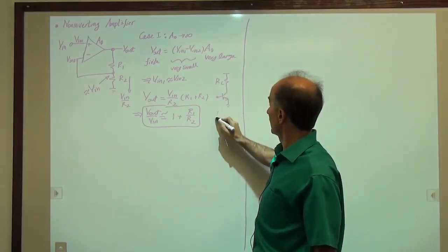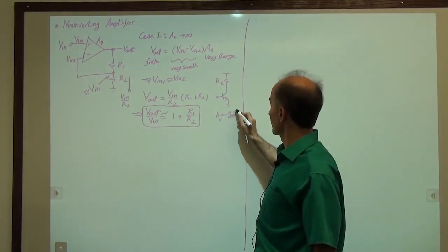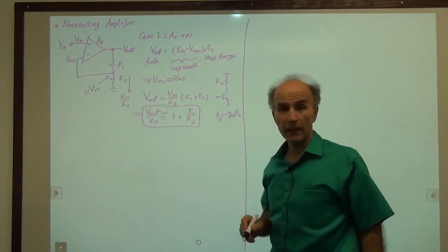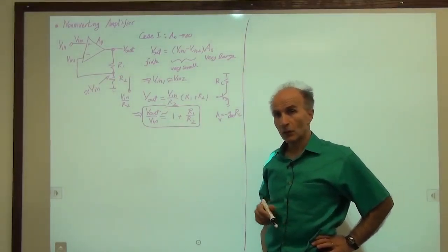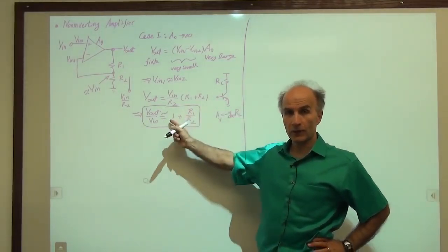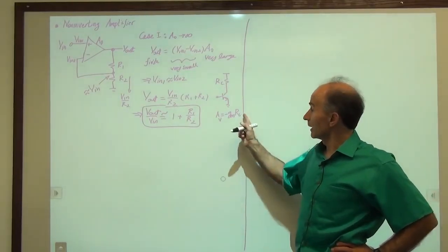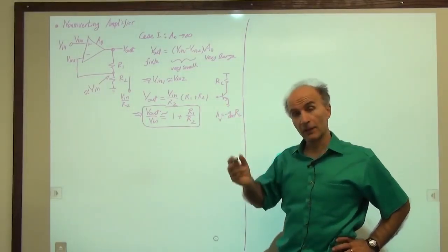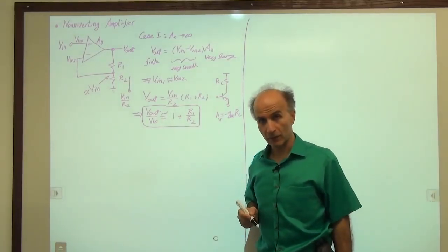And we know that the gain of this guy is given by minus gm RC if we neglect early effect. So we are not happy with this voltage gain, and that's why we go to this amplifier topology. The reason being, if you remember, this has dependencies upon many things. It depends on process and temperature and supply voltage.